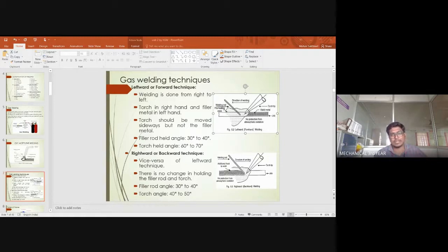So let us see what things are available here. As I discussed, as in your gas welding process, we have a regulator and we have a pressure gauge also. The working pressure is monitored with the help of the gas pressure gauge. We also have a gas cylinder over here, and the electrode is connected to the electric power supply. Here you can see the tungsten electrode is present, and there is no continuous supply of tungsten over here. Which means that the tungsten is considered to be the non-consumable electrode.